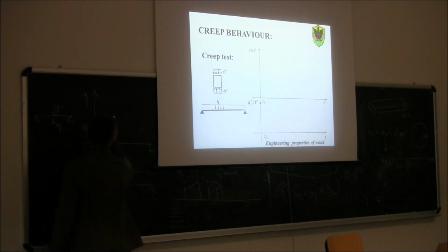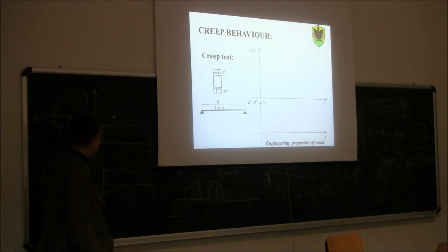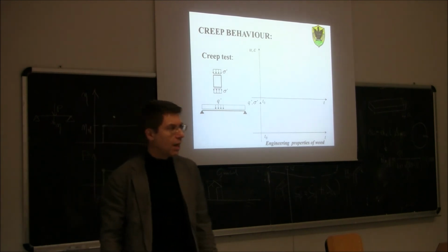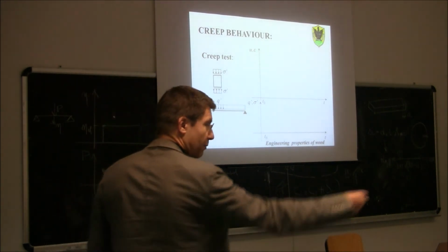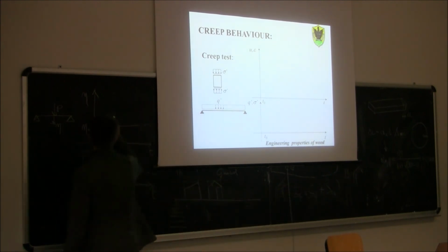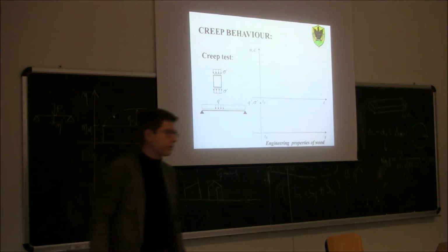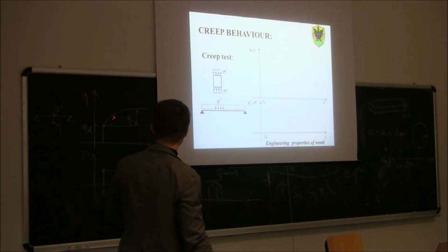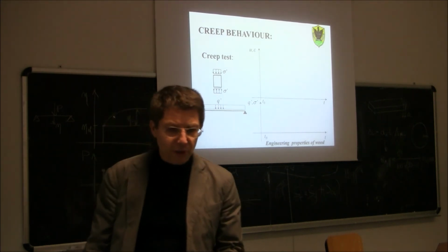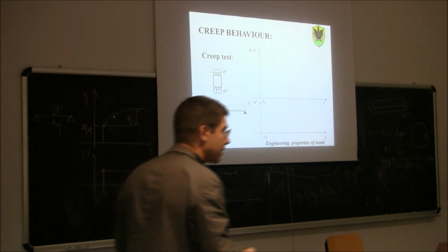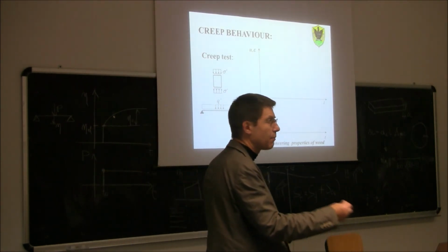So for the steel it would be something like this. Now, if this beam was made of concrete, how would this curve look? The one that you were saying before, exactly. So this would be for concrete. There would be basically what we call a creep deformation over time. As you can see, there is a curve like this. So the creep phenomenon is characterized by an increase in deflection or deformation under the same load over time.